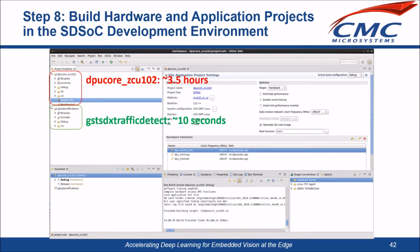As I mentioned, there are two parallel development phases in SDSoC. The first one is to create the hardware, which is the DPU core project. And the second one is to generate the Gstreamer plugin, which runs on the ARM processor, accelerated from the DPU.